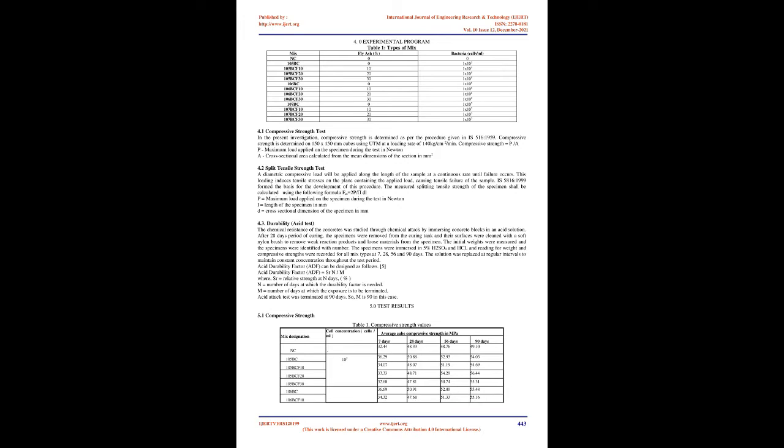In order to overcome this, a special type of concrete is developed with the introduction of bacteria in concrete, which results in bacterial concrete. This is also called self-healing concrete. In view of the global sustainable development, it is imperative that supplementary cementing materials be used to replace large proportions of cement in the concrete industry. The most available supplementary cementing material worldwide is fly ash, a byproduct of thermal power stations, which indicates that there is a potential for the use of much larger amounts of fly ash in concrete, and therefore, for significant reductions in cement production, resulting in considerable environmental benefits.